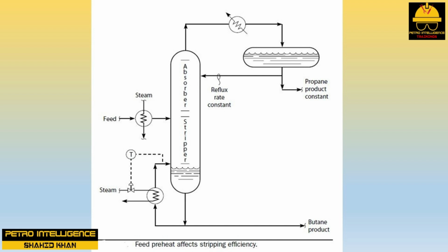that the weight flow of vapor leaving the top tray is also constant, regardless of the feed preheater duty. Actually, this statement is approximately true for all the trays in the top or absorption part of the tower. Another way of saying this is that the heat input to the tower above the feed tray is a constant. But for the bottom stripping section trays, a reduction in reboiler duty will directly reduce the vapor flow from the reboiler to the bottom tray. This statement is approximately valid for all the trays in the stripping section of the tower.